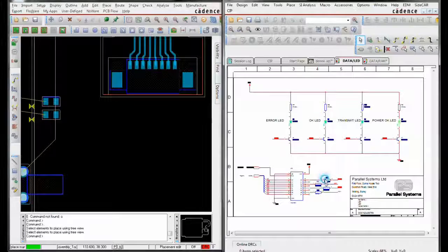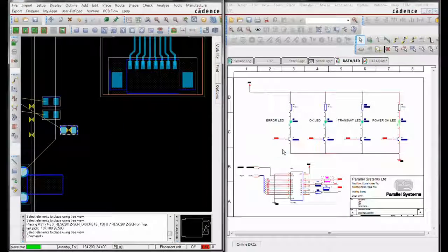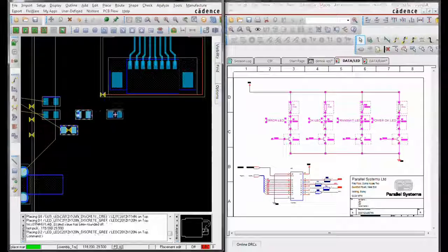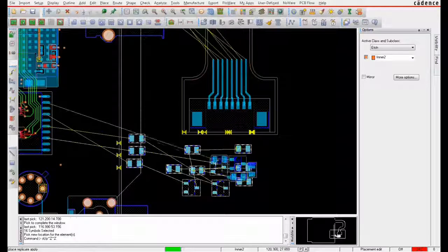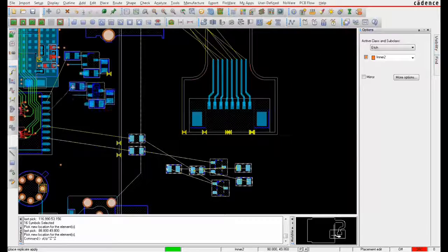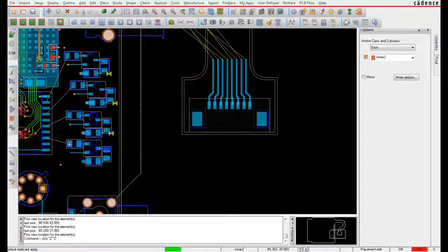Cross Probe allows you to select a component in the schematic and have it zoom to its location in PCB Editor. Users can lasso a section of logic and the components are ready to place in order on the PCB. Design reuse lets you use existing design IP inside the current design or across multiple designs.